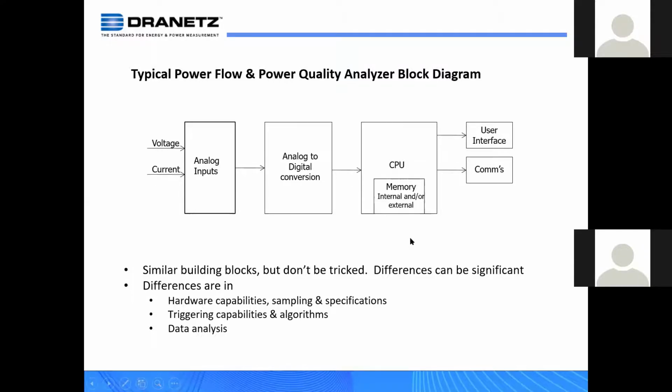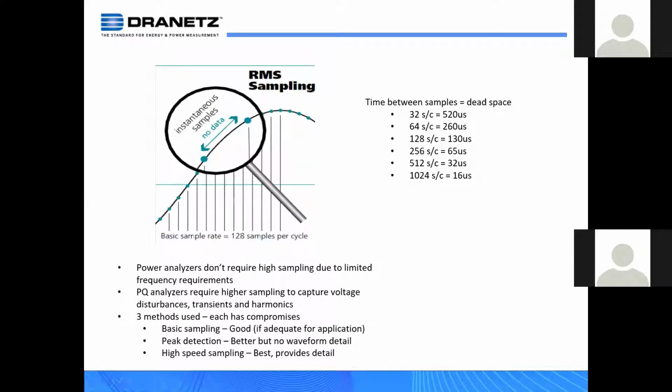However, one of the biggest specifications before we move on here is the digitization and sampling. And the way digitization works, and you can see by this kind of roller coaster image here, is this is an AC sine wave. So imagine that continuing along. Digitization is the instrument takes a measurement, and then X number, in this case, microseconds later, takes another measurement.